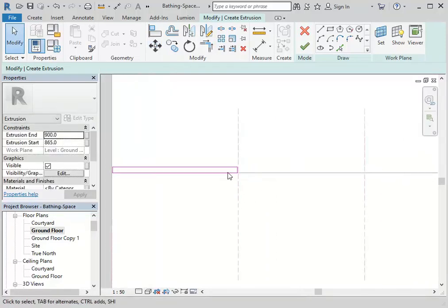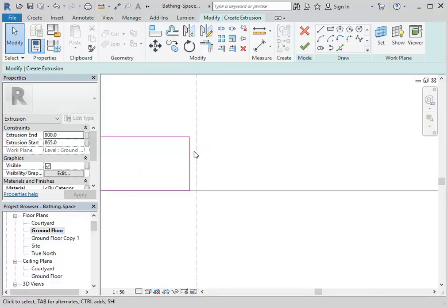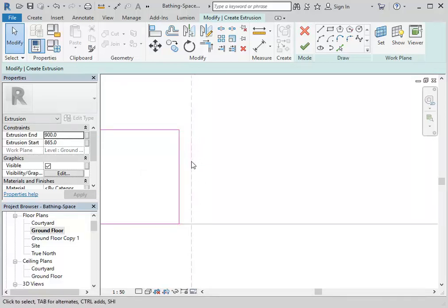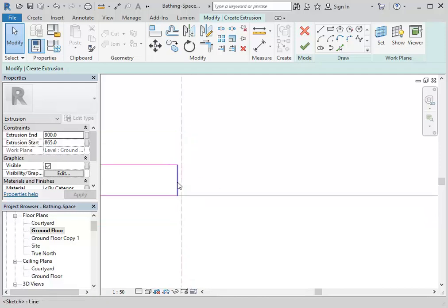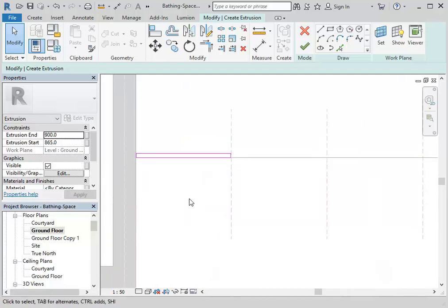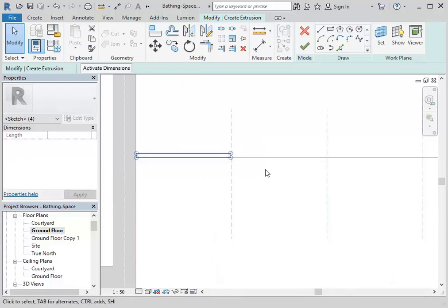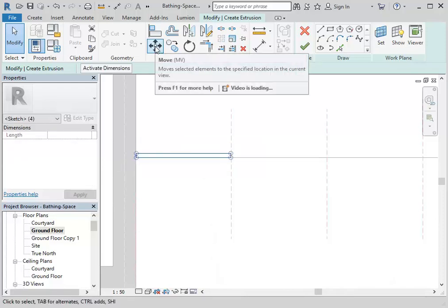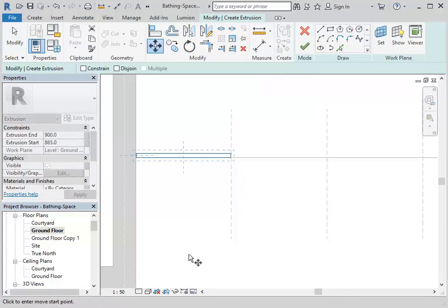That's because I want a 5 mil gap between this one and the next one, with that reference plane centered, in other words, 2.5 mil from the door. Still not perfect, but it'll look just fine. Can you say how you get it? Oh yeah, I just selected the rectangle, clicked move, then clicked the base point, moved in the direction, and typed in the distance.